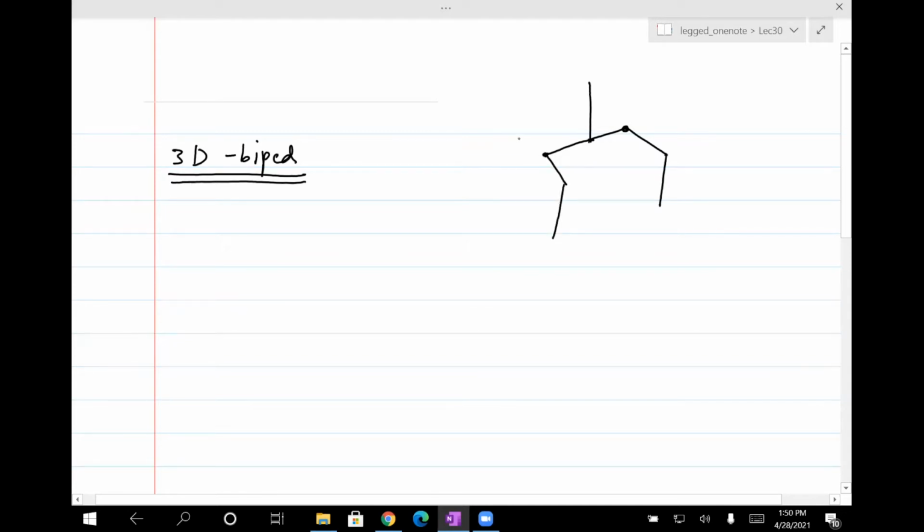Okay, so there are 3 joints here, 3 joints here, 1 joint here, 1 joint here, and they're all revolute joints. And then we need to describe, so these joints are the joints where you have motors, right? You also need to describe the orientation of the robot with respect to the world frame. And there are many options here. You could describe that with respect to this link, this link, this link, whichever you want.